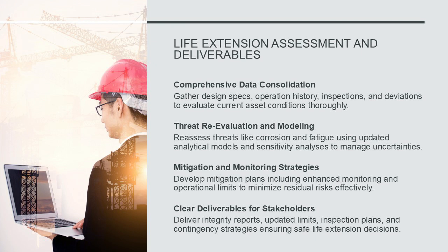Threats such as annulus flooding, armor wire degradation, and fatigue usage are re-evaluated against current conditions. Analytical models are updated to reflect metal loss, corrosion rates, and dynamic loading scenarios, incorporating sensitivity analyses to address uncertainties. Mitigation plans, such as enhanced monitoring or operational restrictions, are developed to manage residual risks during the extension period.